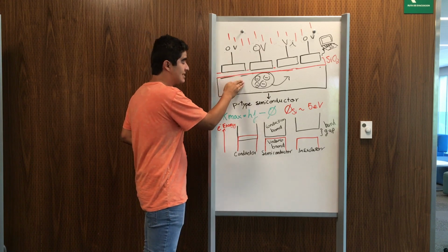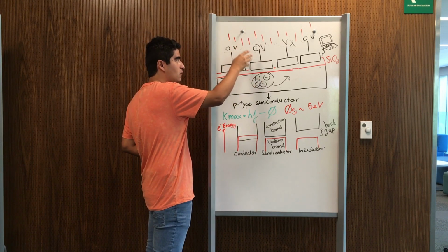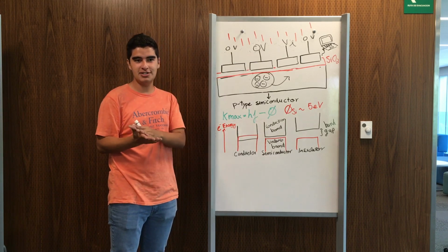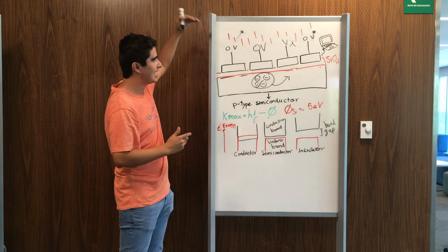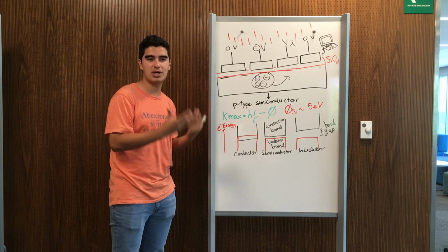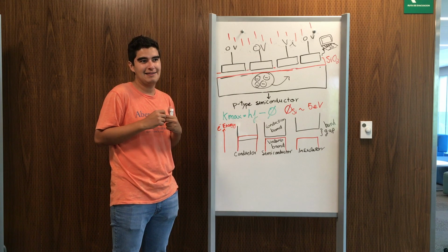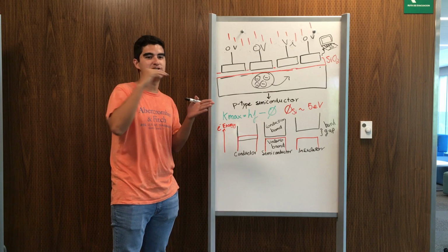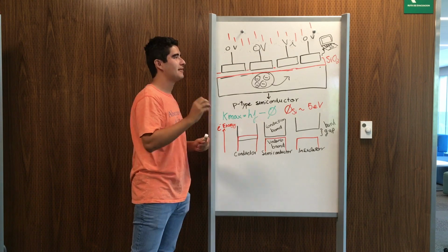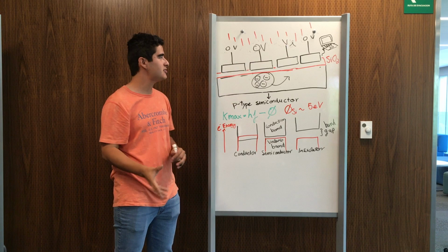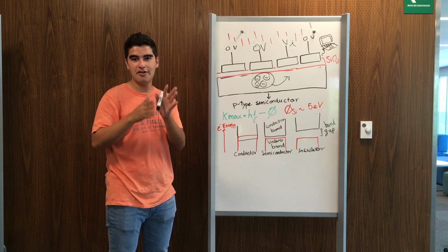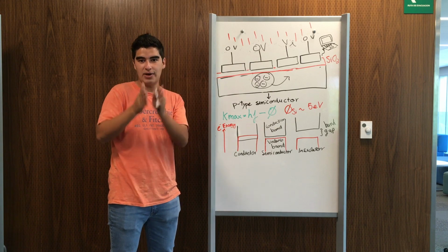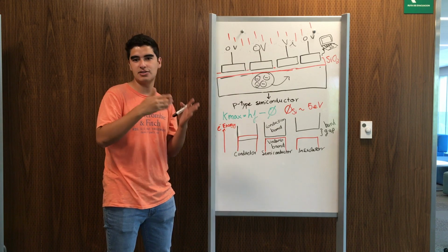Furthermore, since charge is stored below each electrode, the amount of charge is proportional to the light that is incident into the sensor. And this way the sensor can work as a detector for the light that is being transmitted into the spectrometer. This way, each photoelectron corresponds to a specific array of pixels, which also correspond to a specific range of wavelengths that is being incident into the sensor.